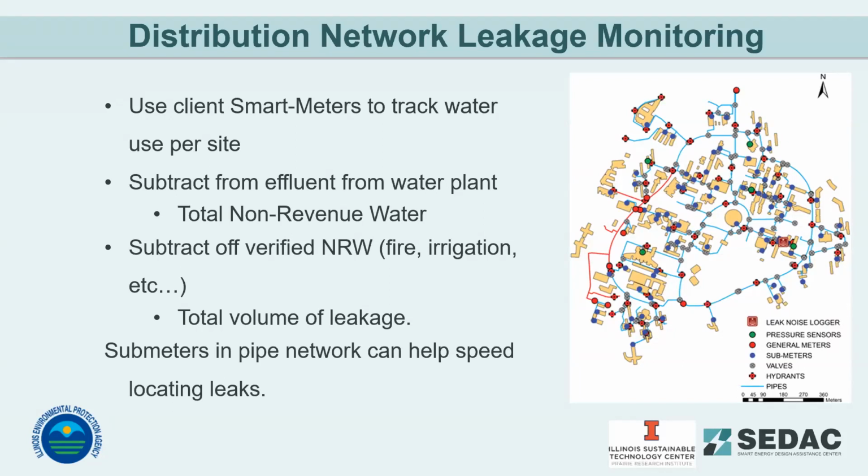You have to assess the current energy baseline status. What do we want to save? You have to know what your benchmark is. And then you've got to perform an energy audit, as we're talking about today. How do we save this? Identify the activities and operations that consume the most energy or are the least efficient. Establish an energy vision and priorities for improvement. Identify, evaluate, and prioritize potential energy improvement projects and activities.